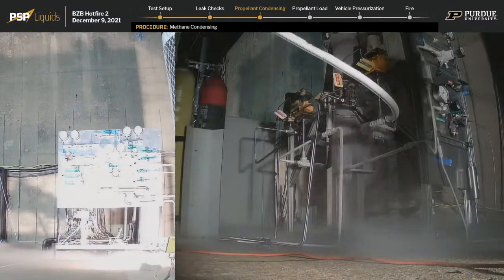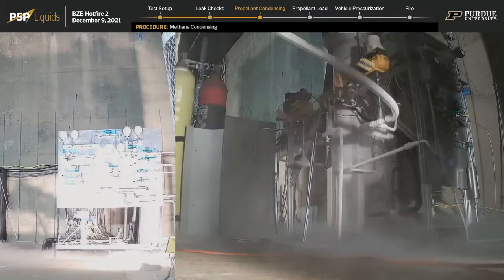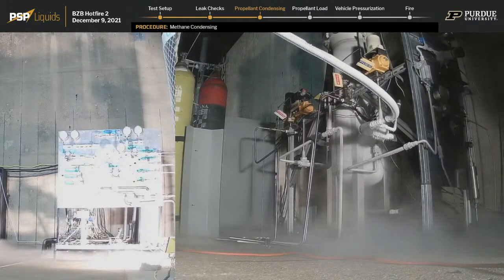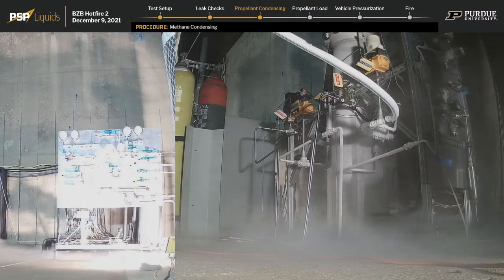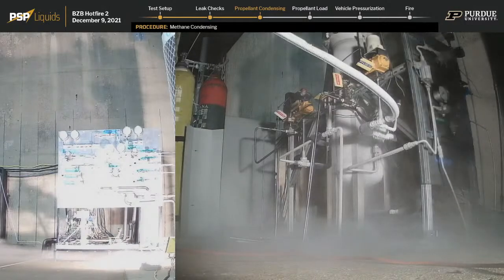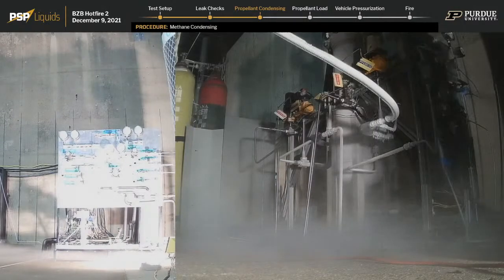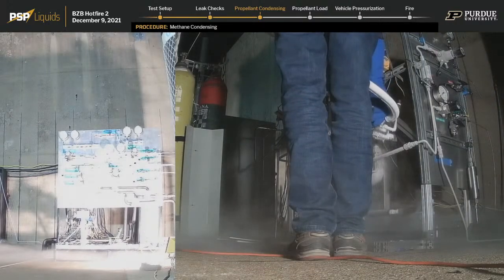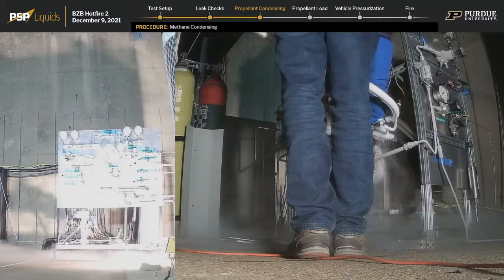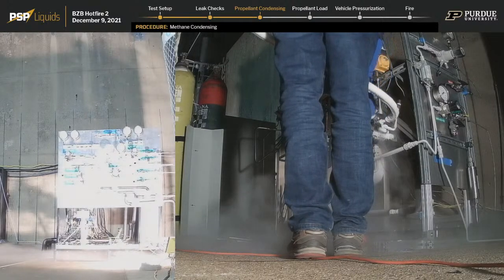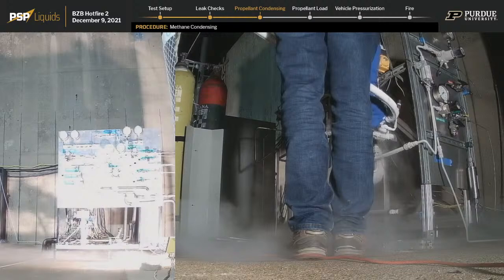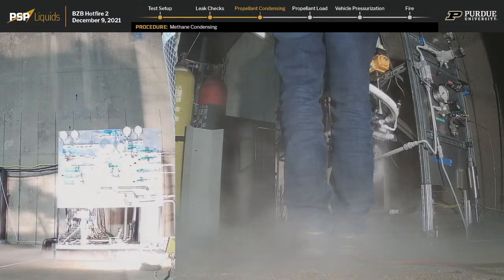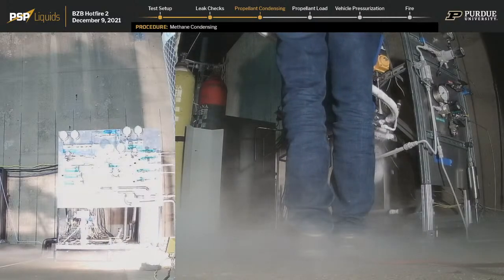So, we have a question in chat. Are we using a COTS COPV for a pressure intake? So that has a few questions. Do you want to go over the definition of COTS, COPV, and then talk about what we did for our pressure tank? Yeah, so COTS, or commercial off-the-shelf, stands for essentially a technology you can purchase directly from a vendor and integrate into your system. And COPV stands for composite overwrap pressure vessel. Think scuba tanks, or lightweight scuba tanks, or firefighter air tanks, which I believe is what our COPV is. Yes. If I'm not wrong.